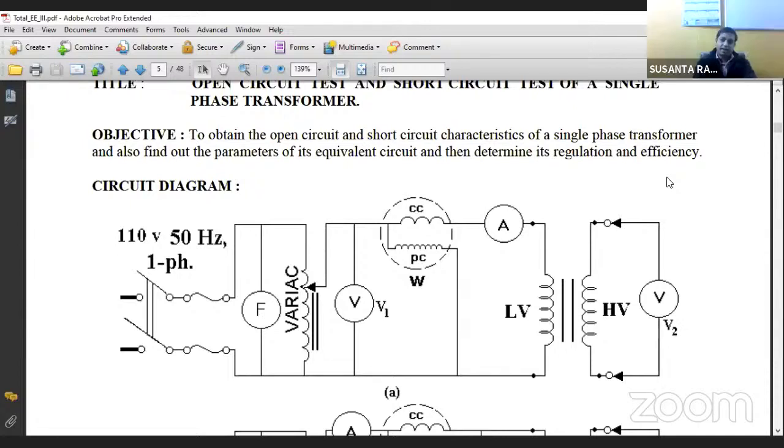Now if we connect the meters, that is the ammeter, and also the current coil of the wattmeter, because the current coil of the wattmeter is similar to an ammeter. It senses the current for measuring the watts. So these two things, the current coil of the wattmeter and the ammeter, as the current is very low, sometimes they cannot measure that low current, or they can measure, but the percent of error can be high.